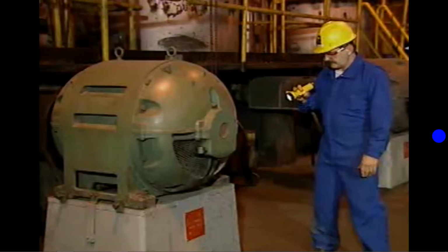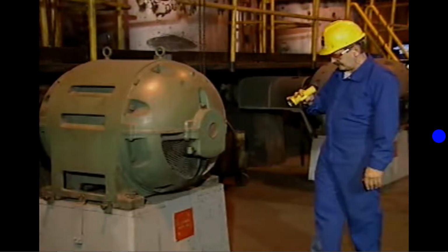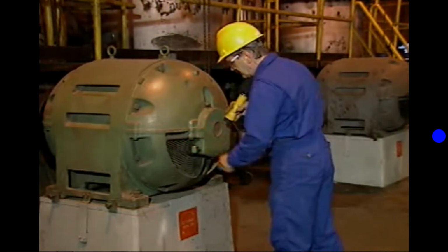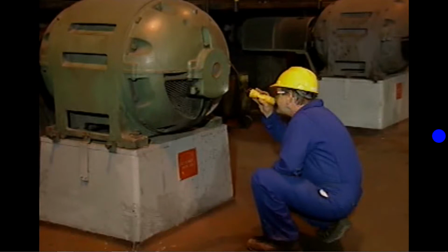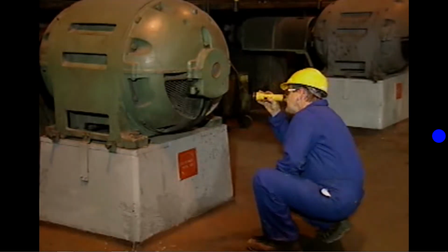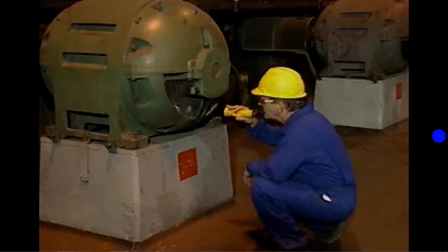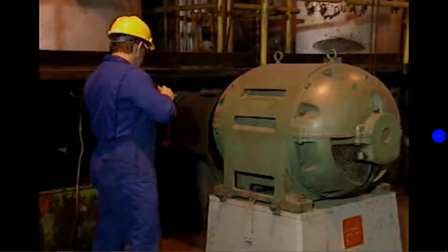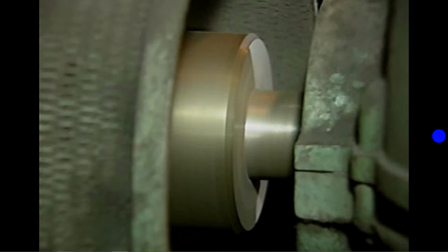If visible, the motor's insulation should be checked to make sure that there are no burnt areas. The bearing housing should be checked to make sure that there is no leaking grease or oil, and the entire motor should be checked for signs of dampness. A complete check of a motor includes inspecting it while it is running. To do this, the motor branch circuit must be put back into service. After the motor has been running for a few minutes, it can be checked to make sure that it is